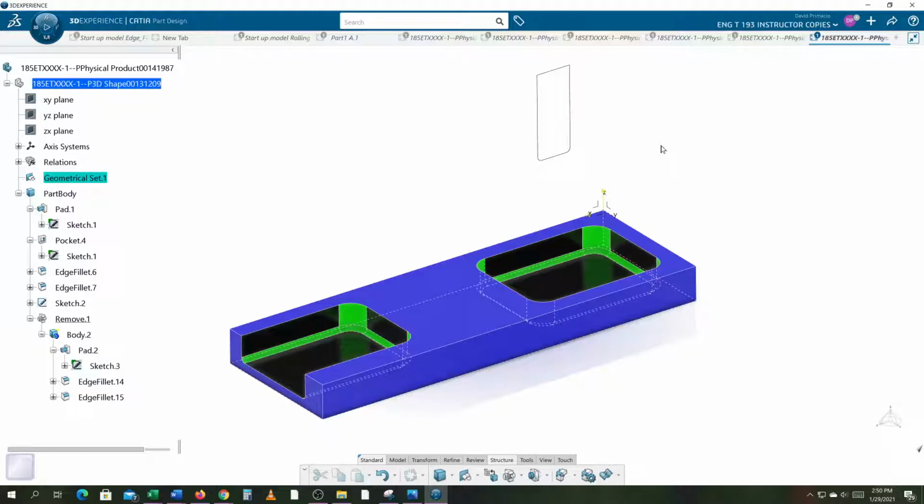Now, when I talk about making engineering parts, we always talk about how things have to be tangent, or you can't have gaps in your geometry. You've got to make sure everything's touching at the same adjacent points where there's no overlap and no gaps. And that's all correct, but really it's important for the NC toolpath to not have gaps or discontinuity and tangencies. So I'm going to try and make a top view of this as if the cutter were drilling down into the part and machining this out to try and explain why a 1/2-inch radius wouldn't be that great if I want to use a 1/2-inch cutter.